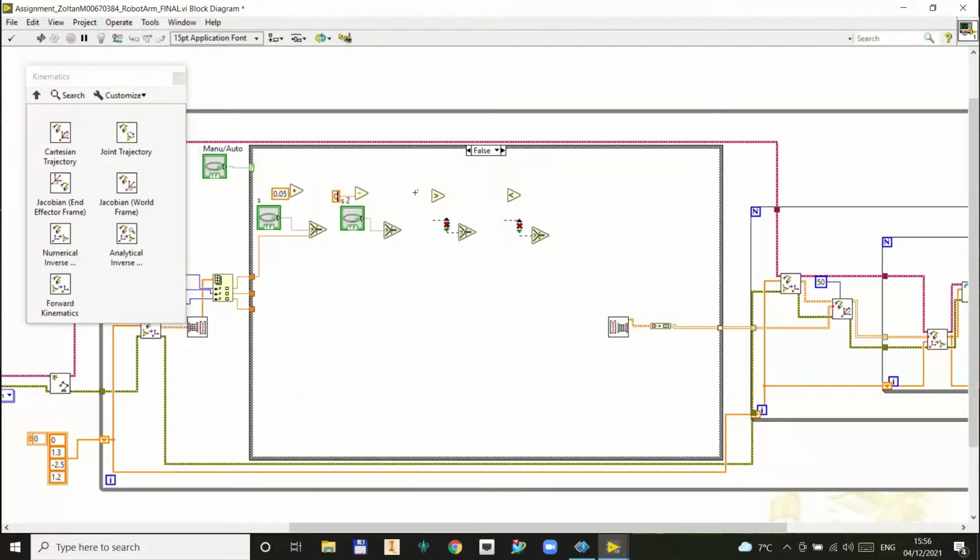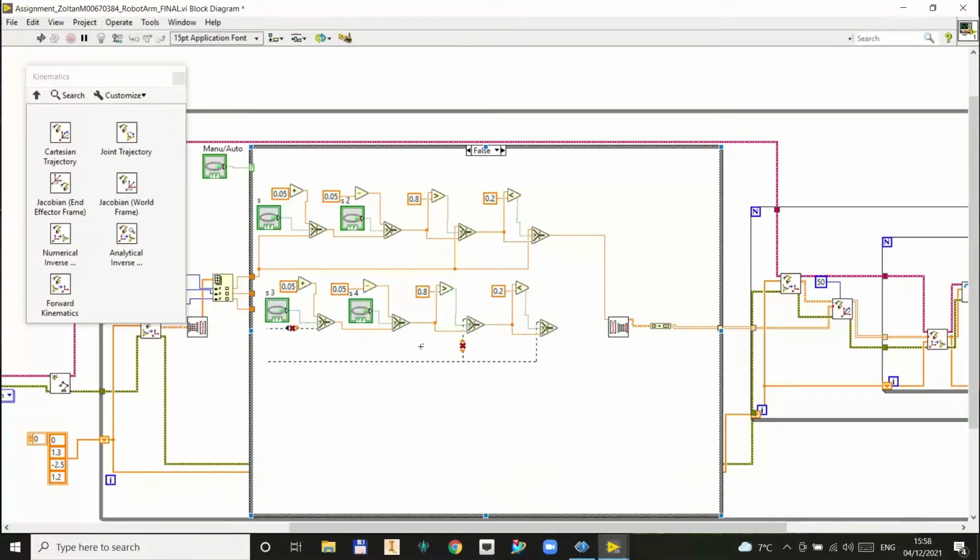To make sure to give achievable coordinates, comparators are used to stay between limits. When the new coordinates are above or below the limit values, the increment values are not used anymore. This way the robot joints will not lock up or bump into the wall.